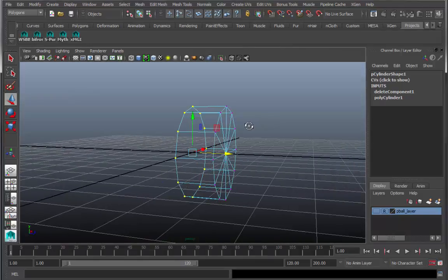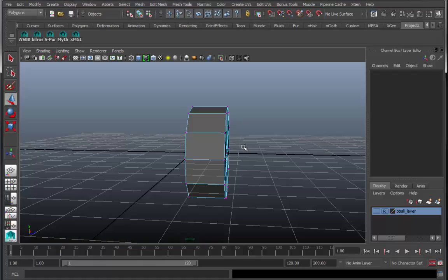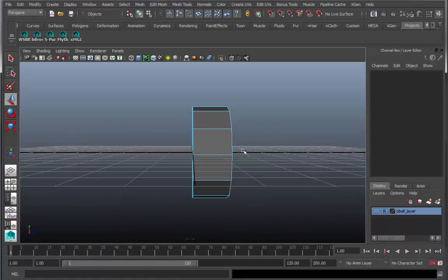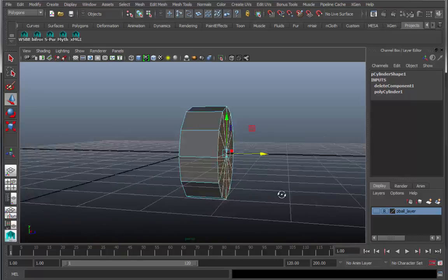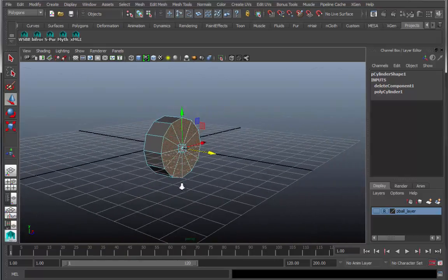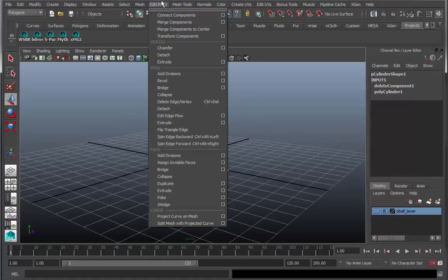Because this side, these faces here, I'm going to start drawing a doorknob by extrusions. So these set of faces, the remaining ones, I'm going to use my little trick of selecting everything and unselecting what I don't want, validating I have just that sort of wagon wheel series of faces selected. I'm going to come up here to edit mesh and extrude again.